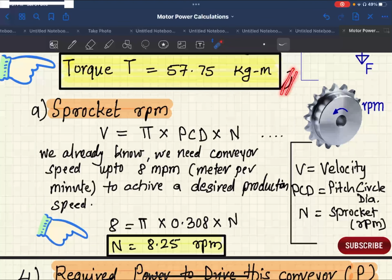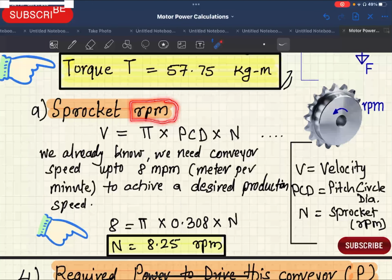After calculating the torque, we need to calculate the sprocket RPM. To calculate the sprocket RPM, we have the formula V, the velocity, equals pi into PCD into N. Why do we need to calculate the sprocket RPM? Because this is required while selecting a motor from its catalog. V is the velocity, P is the PCD, which is the pitch circle diameter of the sprocket, and N is nothing but the sprocket RPM.